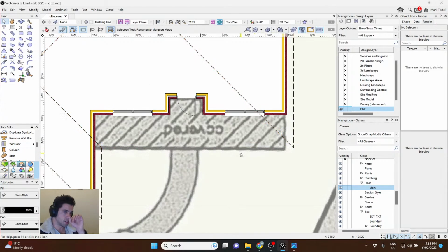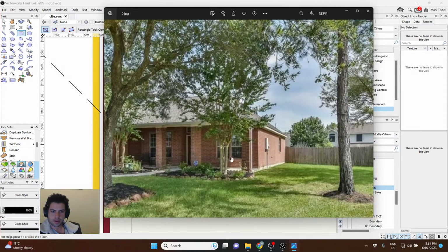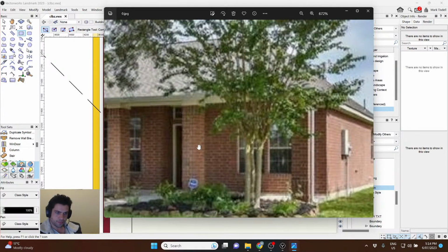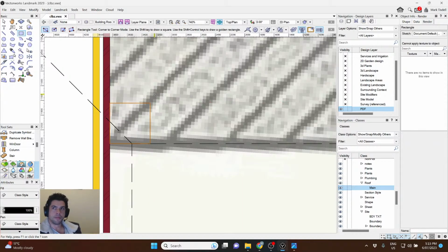With these columns, there is a column tool in Vectorworks. I'm actually not going to recommend that you use it because it can be a little bit finicky. I'm just going to draw it out. And what I might do even is, looks like a double brick, triple brick, let's say it'd be about 550 mils each way.